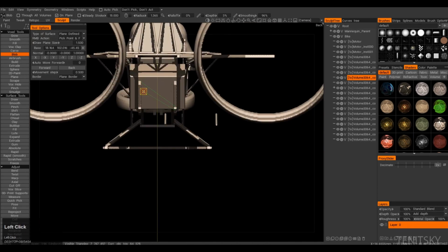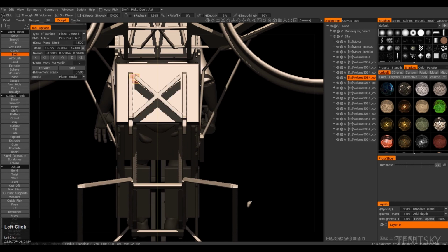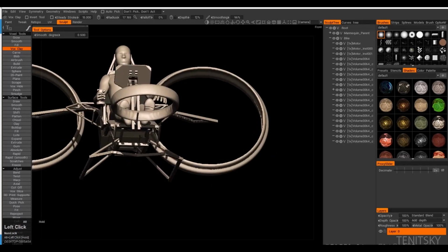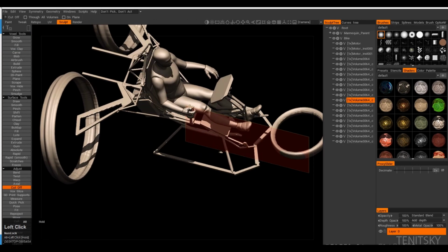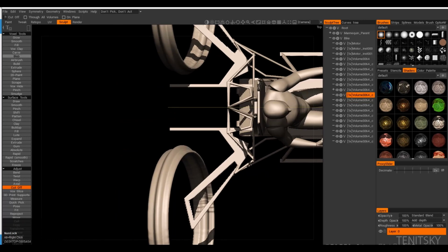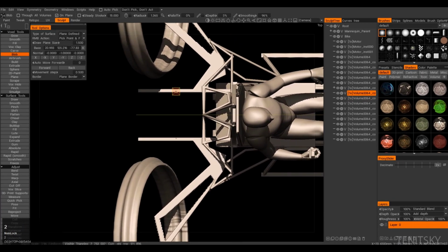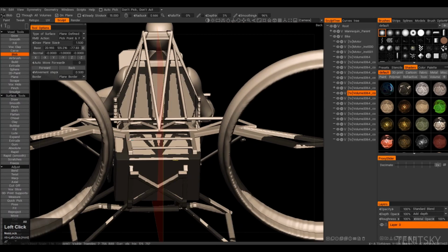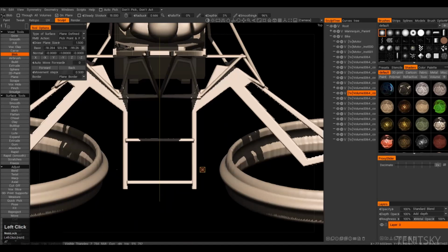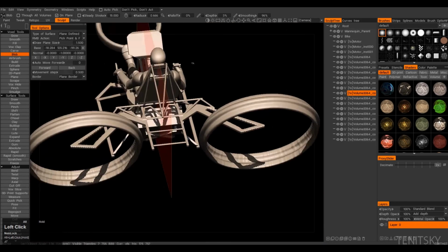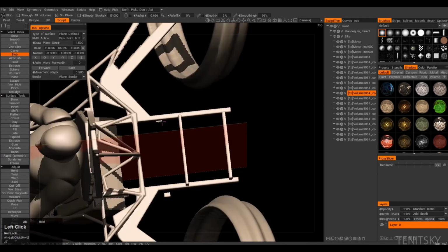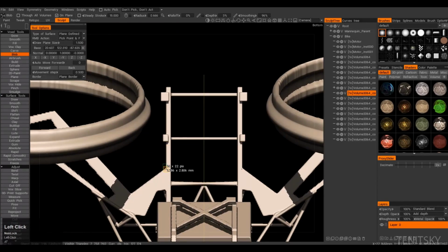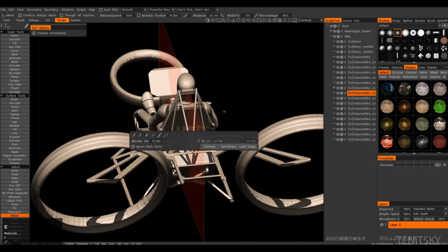I used the sphere tool when I wanted to make an angled stroke from one part of the mesh to another. I couldn't use on plane because on plane is good for these 90-degree angles: left, front, top. But sphere is great if you want to make a frame and connect corners of the frame and make a diagonal connection. But the sphere tool needs something to anchor itself, so we have to build some dots with the on plane tool.